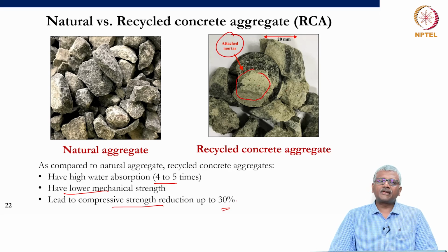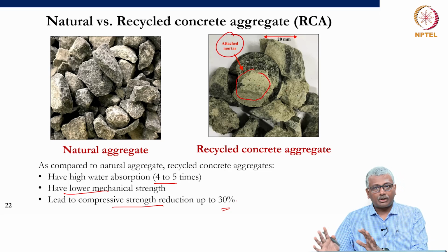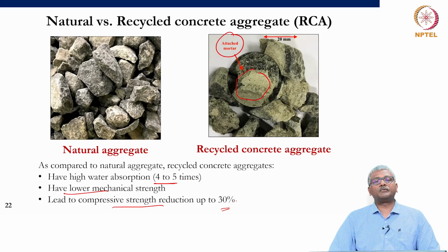Now, is that always the case? No. Why is it not always the case? Because you can derive strategies for optimal processing of recycled concrete aggregate so that it actually ends up giving you nearly the same level of performance as conventional aggregate. And this is something that you will see in the lecture on hardened concrete properties. You will clearly see that recycled concrete aggregates, if the design and development of the concrete is done in a proper manner, will produce concrete which is of as good a quality as your concrete with normal aggregates.